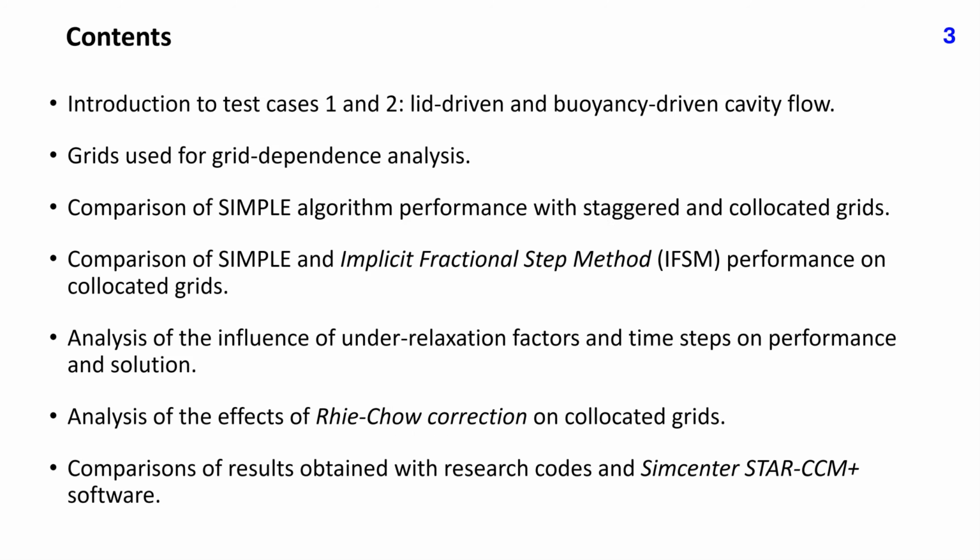Some of the solution methods described in previous lectures were applied to two-dimensional test cases which are widely used for testing solution methods for the Navier-Stokes equations: lid-driven and buoyancy-driven flow in a square cavity. The aim of this lecture is to show how different choices affect the efficiency of the iterative solution process and the accuracy of the obtained solutions.